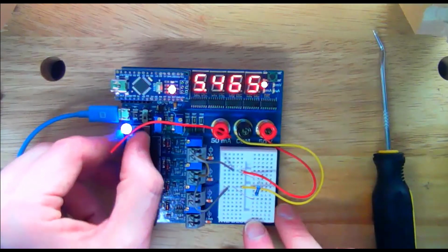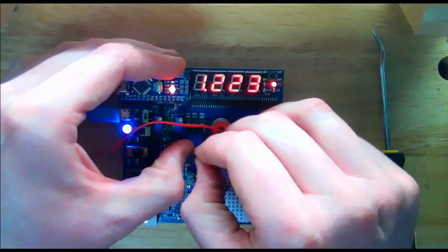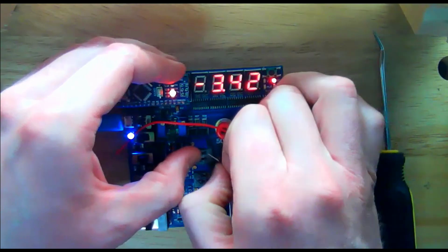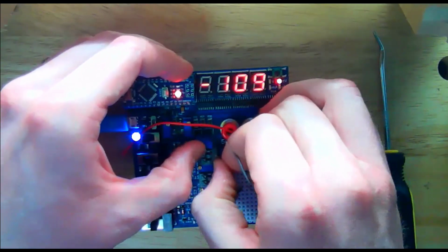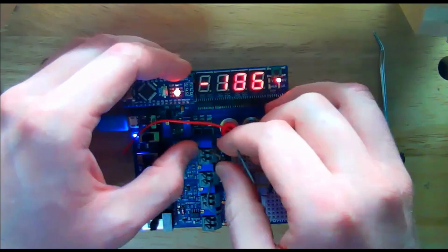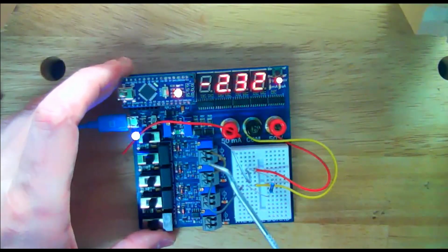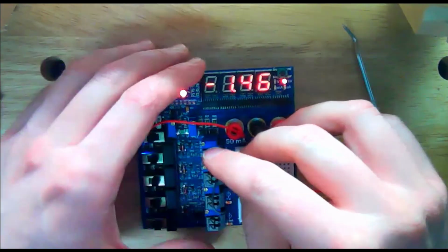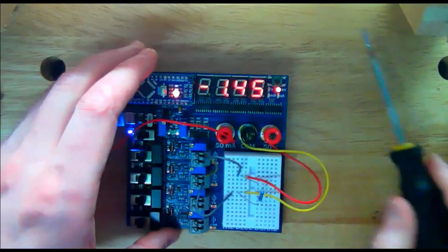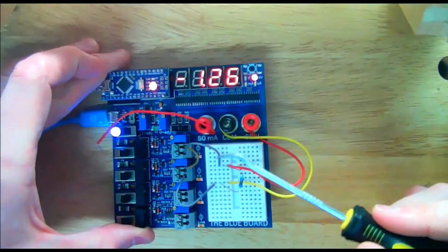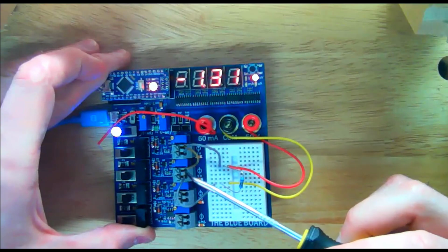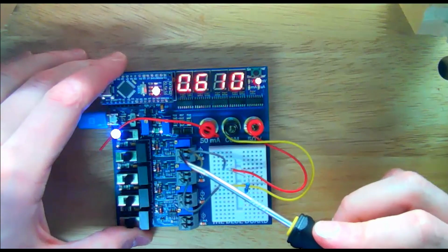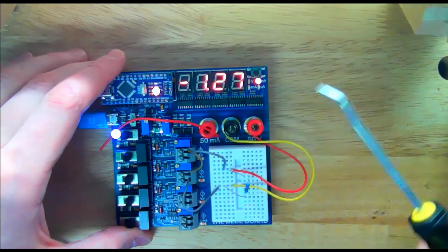So I'm going to de-energize the board, and I'm going to flip around this connection to the 3-volt supply. So the positive terminal of the 7-volt supply is now connected to the positive terminal of the 3-volt supply, and the negative terminal of the 3-volt supply now we're going to connect to our circuit. So I don't know if that shows up on video, but we have this brown wire. Maybe brown's not the best color. Positive terminal of the 7 connected to the positive terminal of the 3, negative terminal of the 3 connected to our circuit.